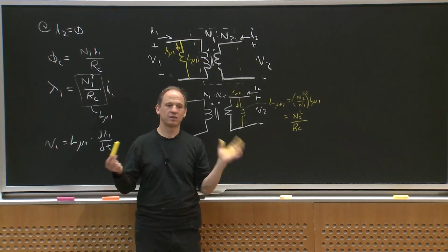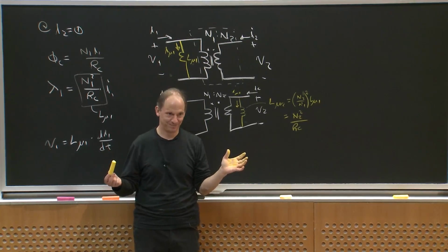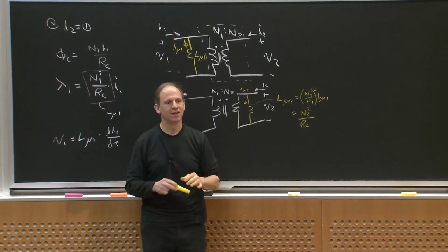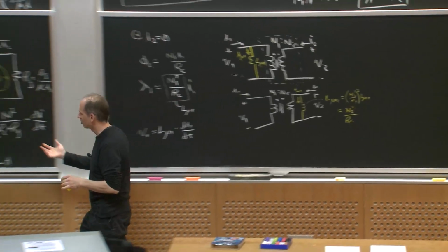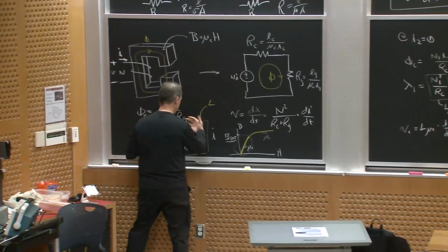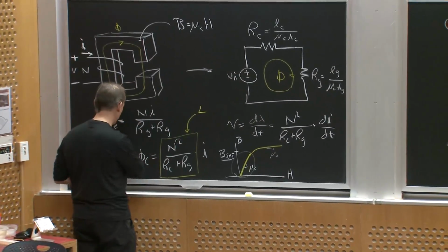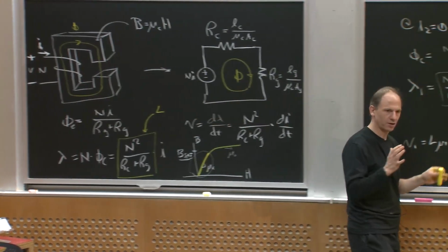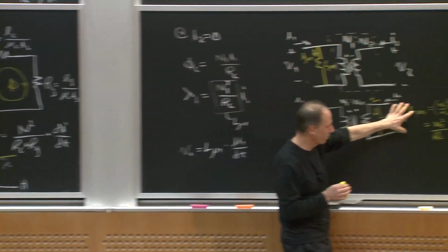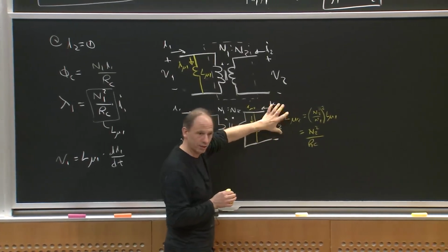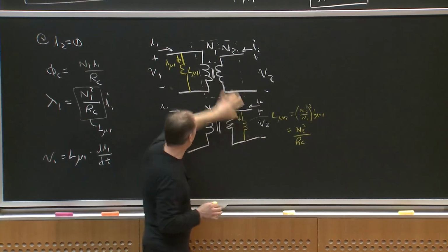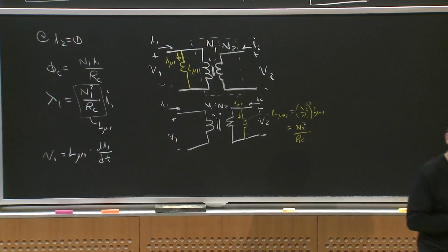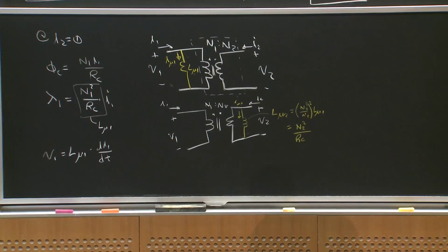The magnetizing inductance has nothing to do with the magnitude of the currents. That's right. And the same way, ideally speaking, in the inductor, the inductance value I get doesn't relate to the currents. It's just the scaling between flux linkage and current. So it doesn't depend on the currents. And if I had some other load out here, I could just keep modeling everything I'm doing. I just need one extra element to model that parasitic behavior. Great question. Any other questions?